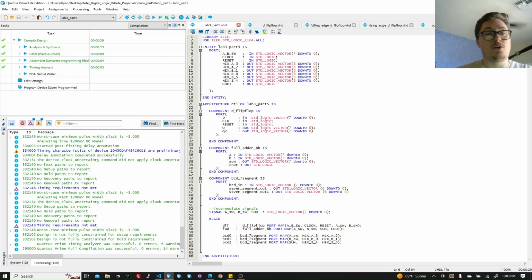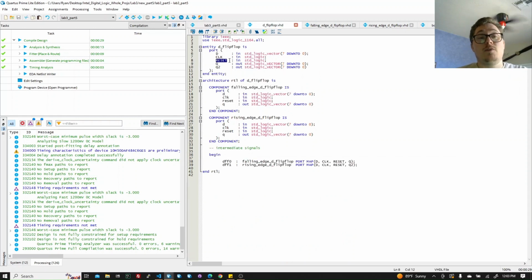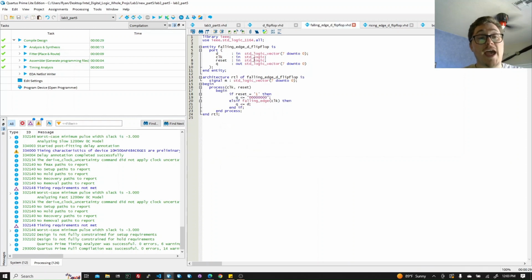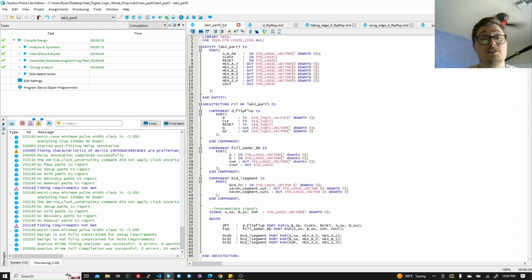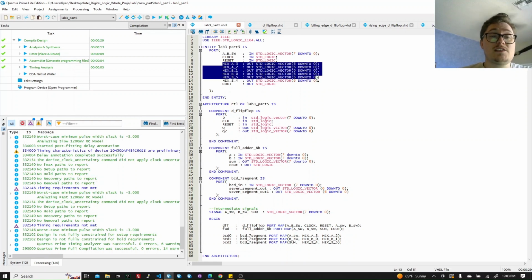We have a clock input and a reset input, and the reset works through the D flip-flop as well. If we pass in a reset, this is connected to both of the D flip-flops, which both have a reset, and if it is reset, the output will be 0 regardless of whatever other input is done through the data switches, which is these here. This is D, essentially.